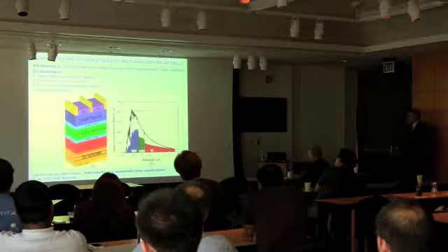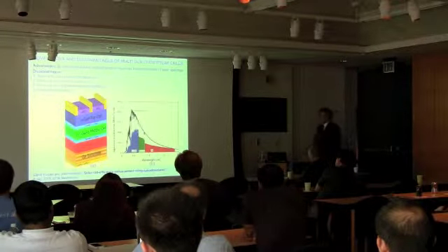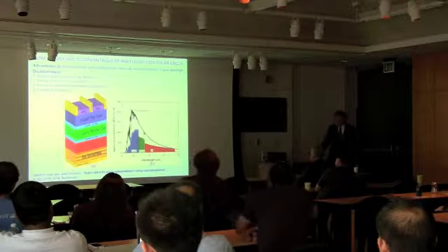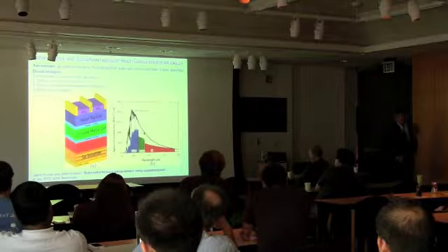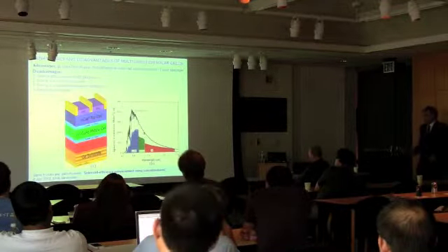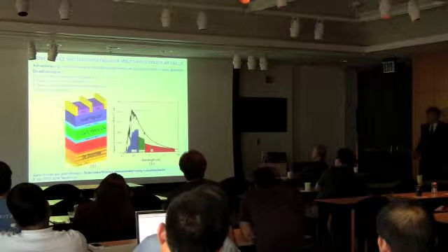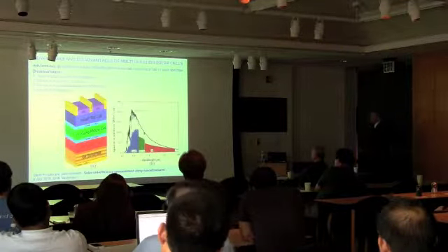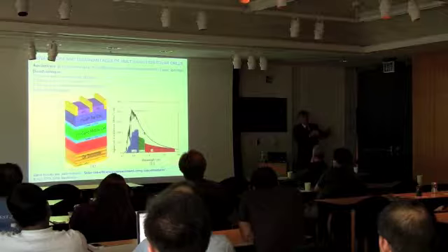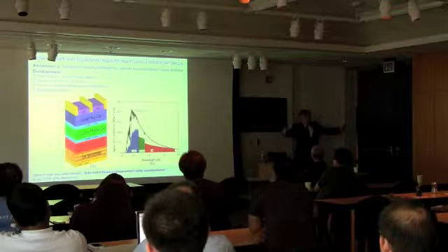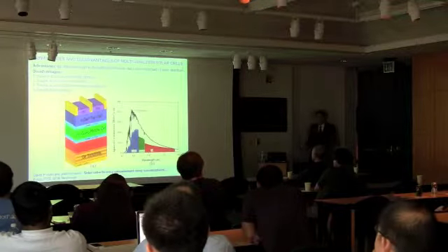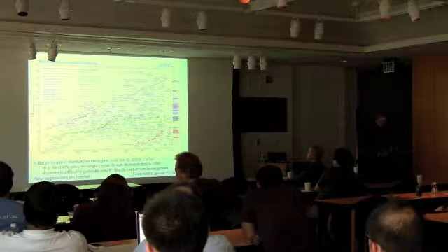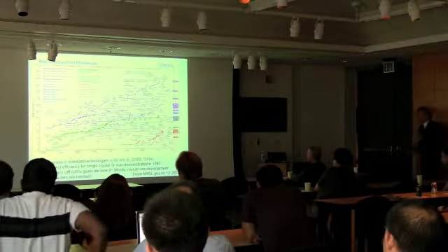But now, you see what else is shown here. At the bottom, we add germanium that absorbs this infrared part of the spectrum. As a result, I will have the same current going through 3 solar cells, but the voltages will be added, and the efficiency of this cell will be higher, because I was able to harvest more energy from the sun and transfer it into useful power.